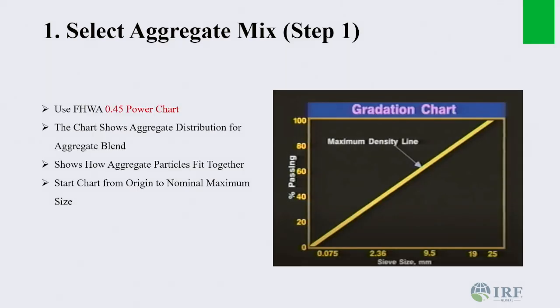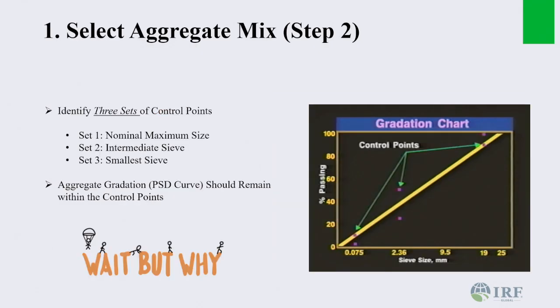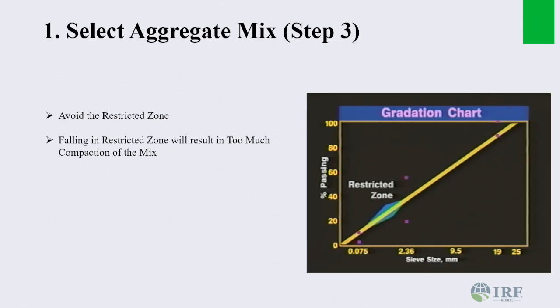So this is what we talked about earlier on, but once again, remember your control points, your aggregate properties, and remain within your control points. Now, and avoid the restricted zone. I talked about this earlier on.